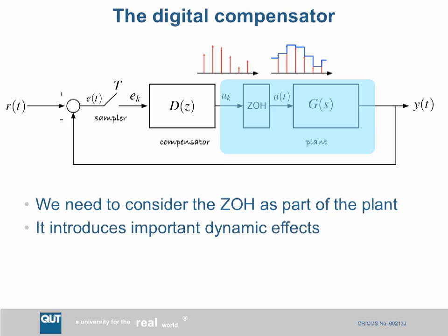So an electrical analog of that is a digital to analog converter, right? You put in a digital value and out comes a voltage, and that voltage keeps coming out exactly unchanged until you write another value to the D to A converter. So a D to A converter implements this zero-order hold function. Its output is constant over a whole sample time. And that's really, really important.